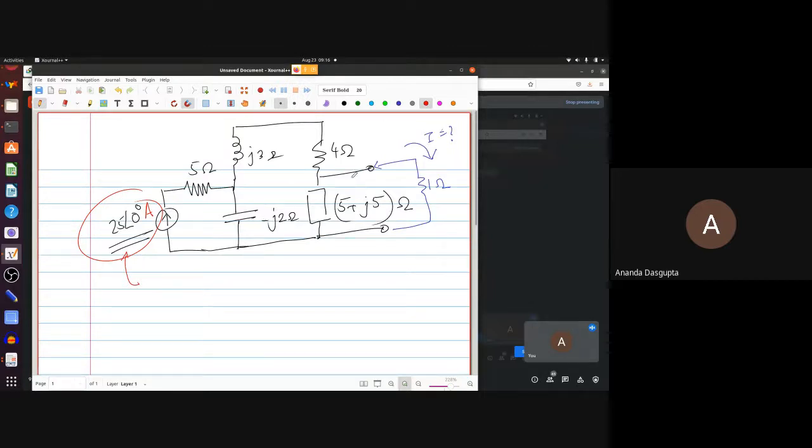For example, when I want to calculate the Thevenin voltage here, remember I want the current through the 1 ohm, and the rule for doing that is to treat 1 ohm as outside the black box. That is, the port should be this one. The one port in the one port network should be this one, to which you are connecting the 1 ohm.